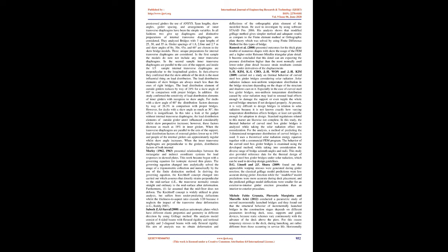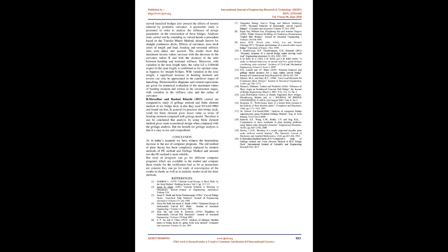Sabir and Al-Saraf, 2008, analyzed anisotropic plates, which have different elastic properties and geometry in different directions, by using the grillage method. His analysis model consists of four-sided beams with flexural rigidity and torsional rigidity and two diagonal beams with only flexural rigidity. His aim of analysis was to obtain deformation and deflections of the orthotropic plate element of the modeled beam. He used software STAAD Pro for the investigation, 2006. His analysis shows that the modified grillage method gives a simpler method and adequate results as compared to the finite element method or orthotropic plate theory, which was solved by using the finite difference method for this type of bridge.